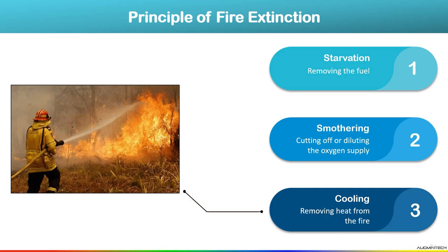But remember here, for electrical fire we cannot use water. If you use water, what happens at that time? It causes electrical shock. In metal fires also we do not use water to extinguish the fire. Same thing for oil fire, because if you use water on metals and oil fires, they increase the size of the fire.